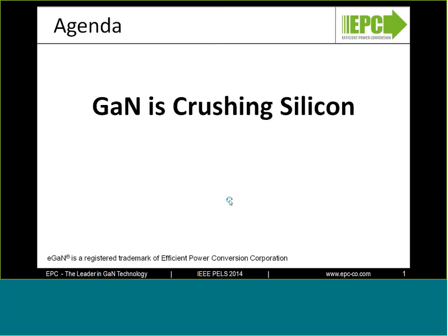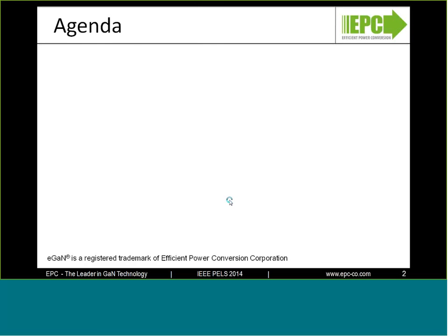We're going to tell you first how eGaN FETs work. eGaN FETs are enhancement mode field effect transistors made in gallium nitride grown on top of a thin film of silicon. They have the opportunity to work 1,000 times better than silicon power MOSFETs. And today, in our early generation of devices, we're running about 5 to 10 times better than silicon, and we'll show you how and why.